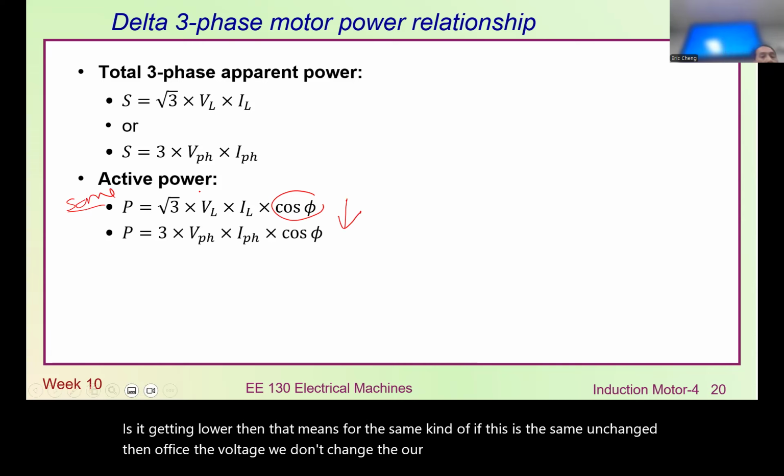So that means the current loop on the input side will just loop in here. We have input voltage here, and because it's a delta motor, line voltage equals phase voltage. And because it's a delta motor, we need to divide the current by √3 to get the phase current. Now we have the phase current, and this phase current will be injected here, with line voltage 400 going to here. Then the power for each phase is the total divided by 3. Now we know the power for each phase. Straightforward, simple enough. Firstly, we get the impedance. The no-load impedance is the impedance around this loop, so that means this loop will be 86.